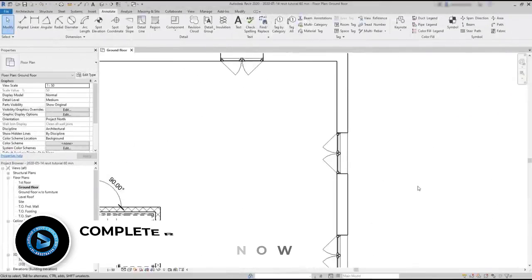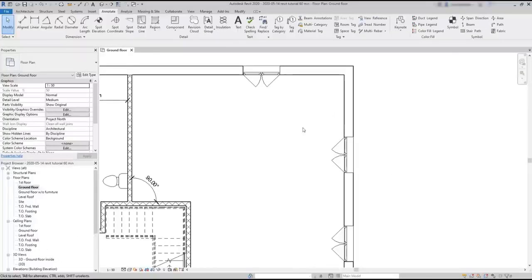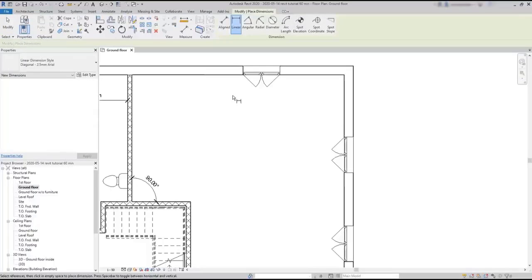More dimension styles. Linear dimensions. These are similar to aligned dimensions, even a bit less versatile. The way they work: I must click in 2 points to place the dimension. For example, I'm going to click on this corner. And there is actually a blue point appearing on the screen, even if it's very hard to see sometimes. Then I'm going to select the point where this window starts as the second point, and finally place the dimension.